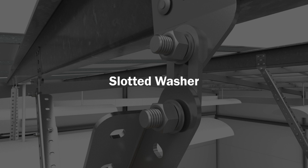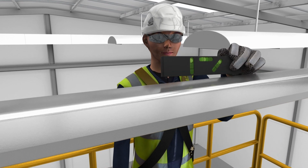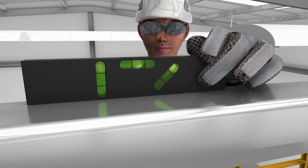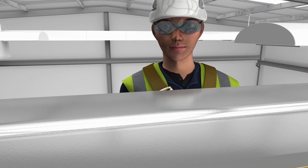Slotted washer. Before proceeding with the installation process, it is important to check the rigid rail is level and running true to the datum. Often, the structure onto which Kee Track is being installed will have a degree of inaccuracy, and minor on-site adjustments may be needed.